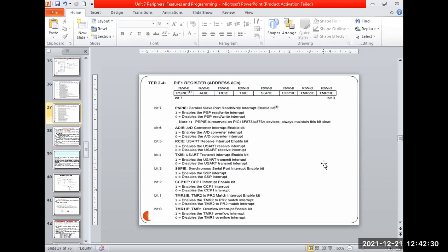Like in the 8051, in the SBUF register, when data is received the RI flag will be set, and when I'm transmitting, the TI flag will be set. Similarly, TXIE is for transmission. Just the nomenclatures are changed here: this will be the RI flag, and this will be the TI flag, as in the 8051.